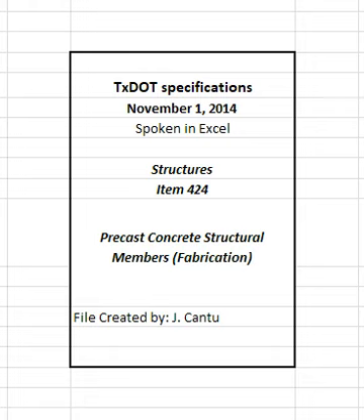Table 2. Temperature probe requirements. See table in specifications. 1. Excluding precast bridge deck panels and precast retaining wall panels. 2. When accelerated curing is used, concrete temperature probes to monitor low concrete temperature regions are not required. 3. After attaining specified release of tension strength. 4. These probes are in addition to the concrete temperature probes required for monitoring high concrete temperature regions. 5. Place probes at the beginning and end of casting line.